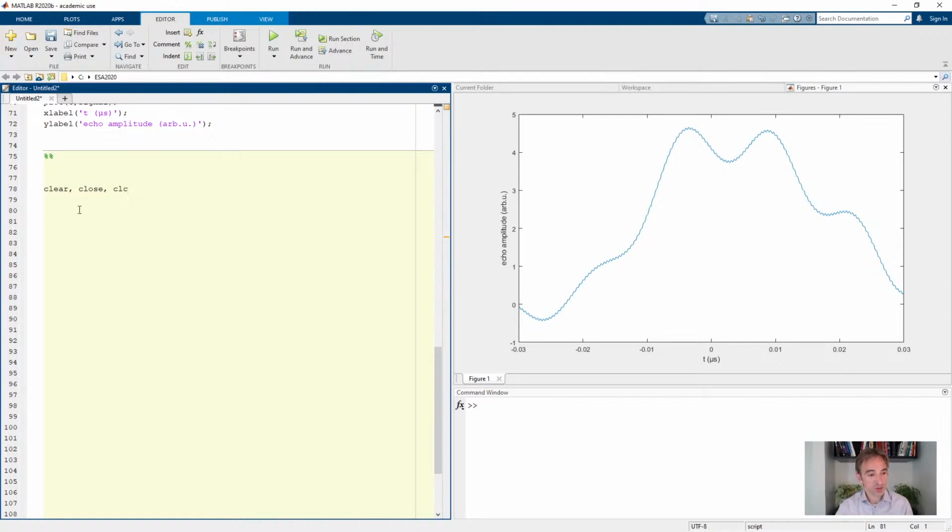Let's define a pulse, and I'm just going to copy paste a pulse definition here. This pulse is called a versed pulse. The versed amplitude is essentially just a soft on-ramp, then a flat amplitude, and a soft down-ramp at the end of the pulse. And linear means we do a linear frequency chirp.